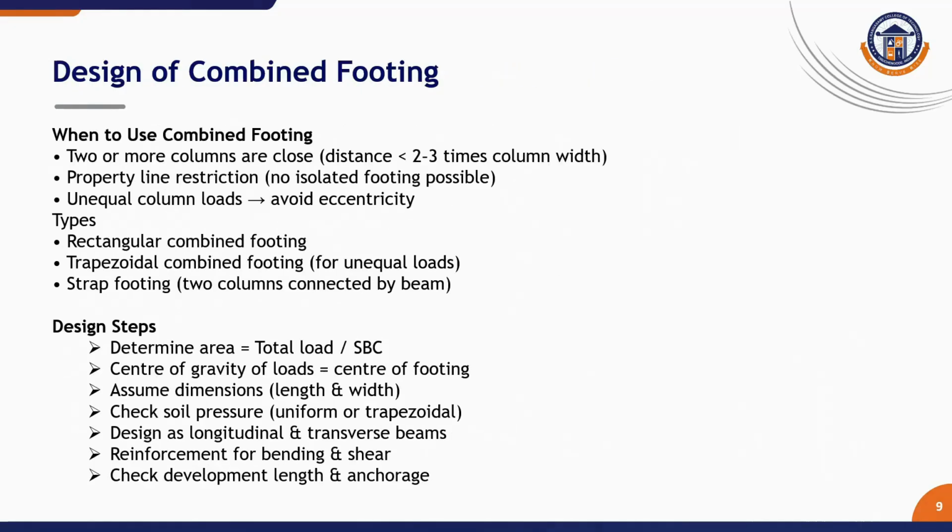As far as IS 456 is concerned, minimum thickness has to be 100 mm or 1 by 30 of the unsupported height. Minimum reinforcement for vertical reinforcement is 0.12% of gross area for high yield strength steel bars and 0.15% for mild steel. Horizontal bars are the same as the vertical.